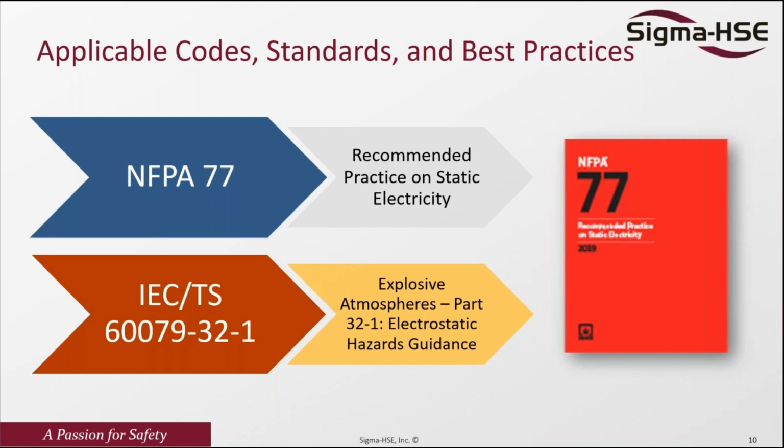So these are the various applicable standards that we normally use. In the United States, we have NFPA 77, the recommended practice for static electricity. So NFPA 77 is always used. In Europe, we use IEC TS 60079-32-1. So that is what is used in the European standard.